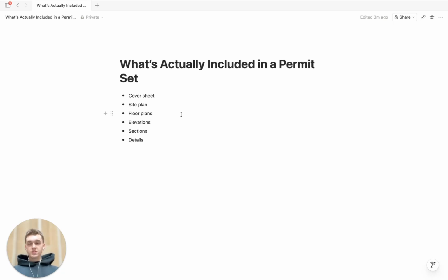Once he approves and stamps everything, and if there are any red lines, you can correct them, go through the checklist and mark off, get everything finished up and done. And then once it's signed off by the structural engineer or whoever's stamping your drawing, essentially the structural engineer or a licensed architect, you can proceed to submit them to the city if it's an architectural designer that's doing the plans. As I'm not licensed or an engineer, but I'm designing the